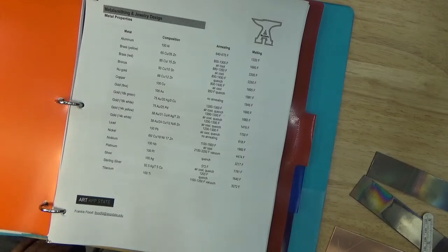while it's at its annealing temperature, versus air cool, which basically refers to letting the metal just cool down naturally. So you would take it up to its annealing temperature and then remove the torch, turn it off, and then just let the metal cool without dunking it. So make sure you know that quenching term. That might be a good quiz question. So quenching just refers to dunking the metal in water once it's up to its annealing temperature.